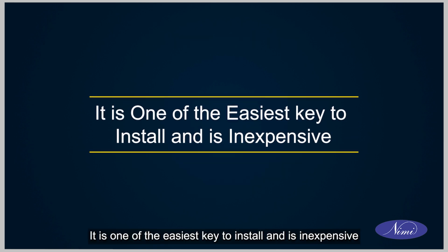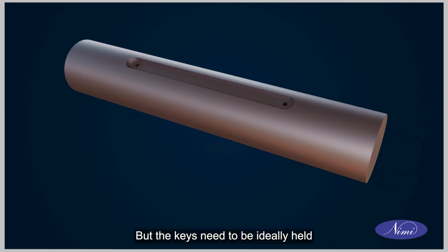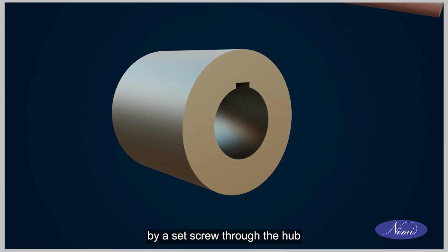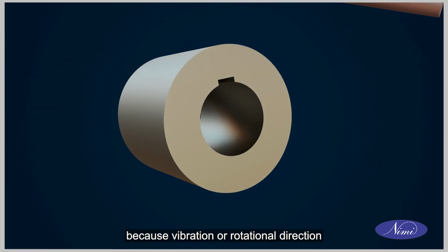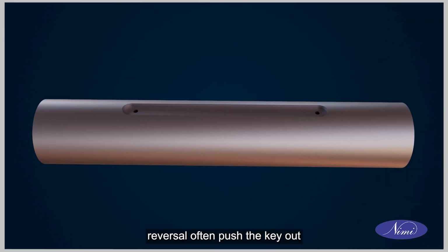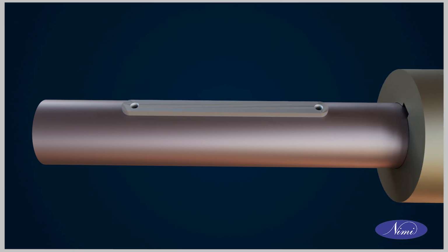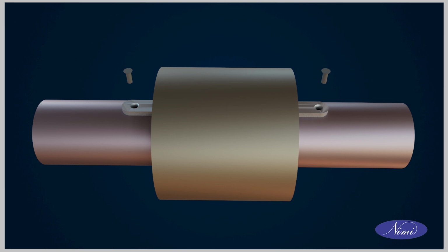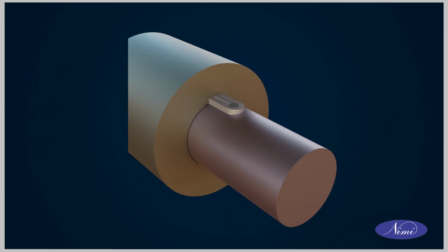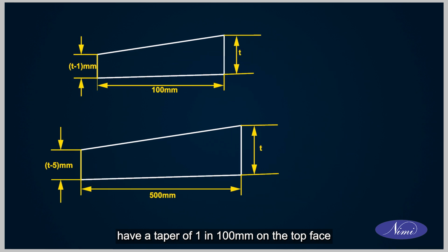It is one of the easiest key to install and is inexpensive. But the keys need to be ideally held by a set screw through the hub because vibration or rotational direction reversal often push the key out. Parallel taper sunk keys have a taper of 1 in 100 mm on the top face.